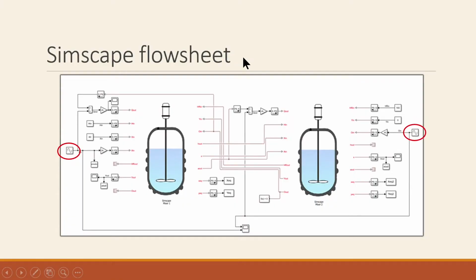This is the countercurrent cascade flowsheet and Simscape of the process, corresponding to the previous code. For the simulation, the configuration can be done flexibly through the user interface. To study the effect of the oscillations, which is a specific objective of the investigation, aqueous and organic flow rates are configured as sinusoidal inputs, keeping the rest of the inputs constant.